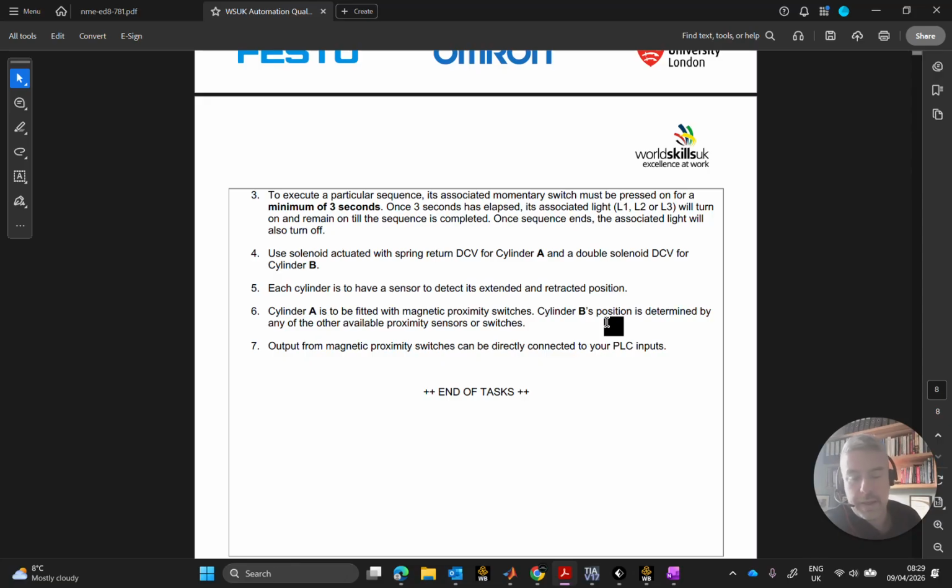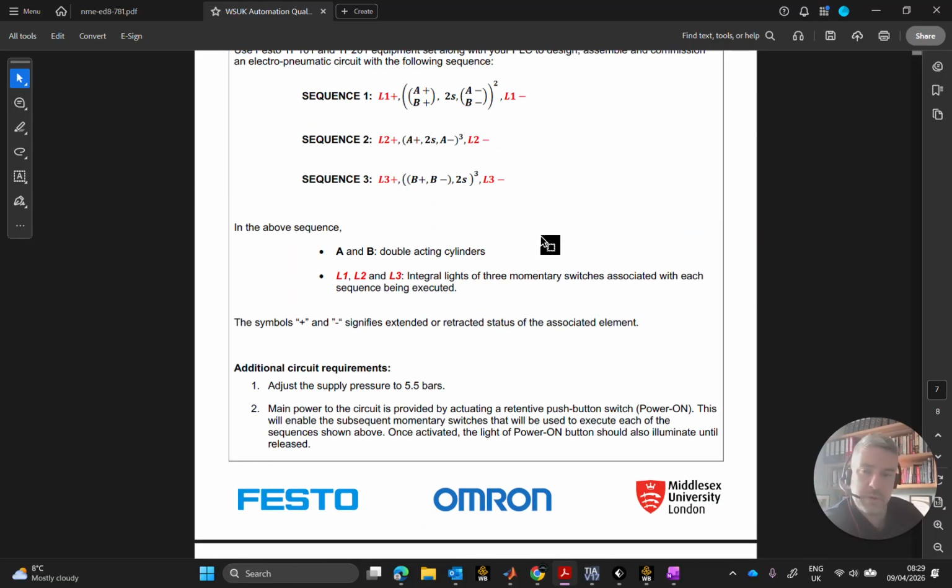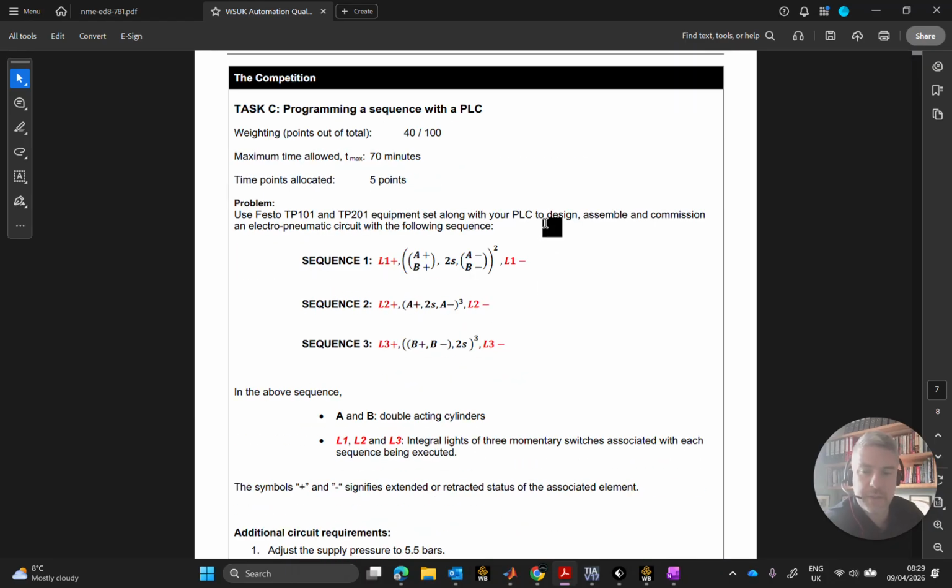We're only going to indicate what solenoid should be energized. How they get energized is really down to what the circuit requirements dictate and what the builder provides, i.e. are we going direct between the PLC and the hardware, or do we need a user relay to create some sort of an intermediary connection.